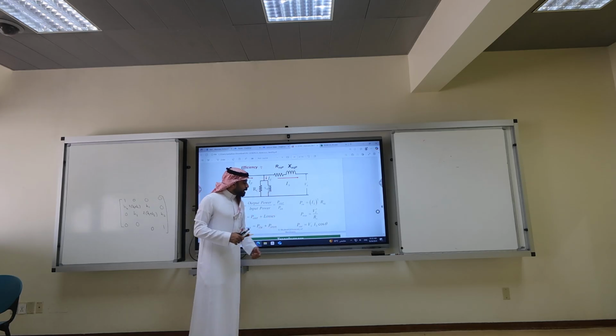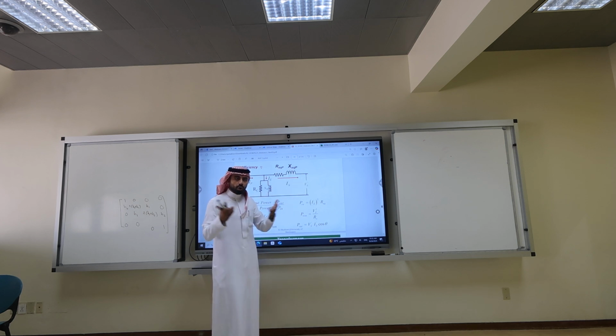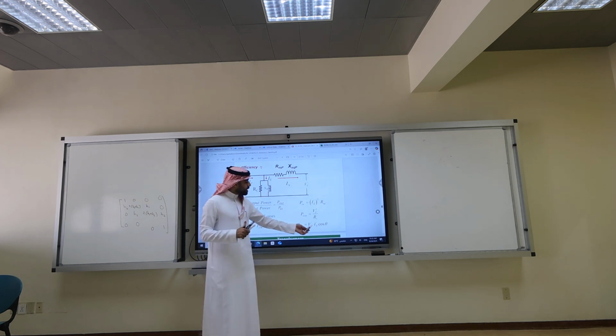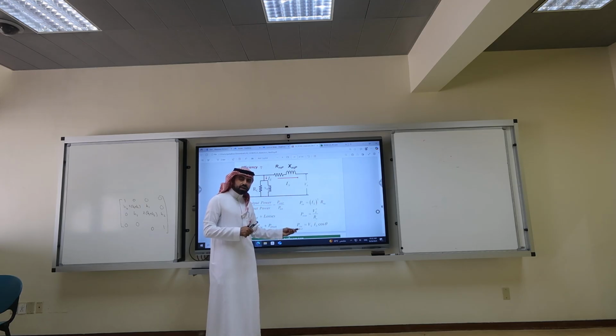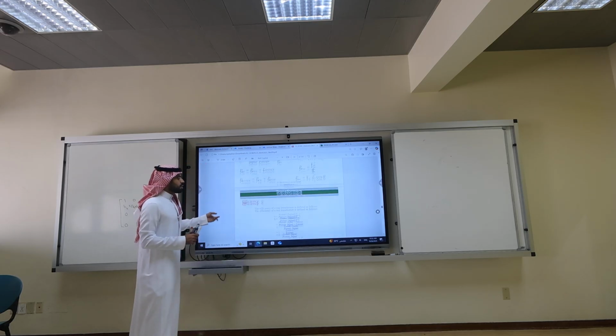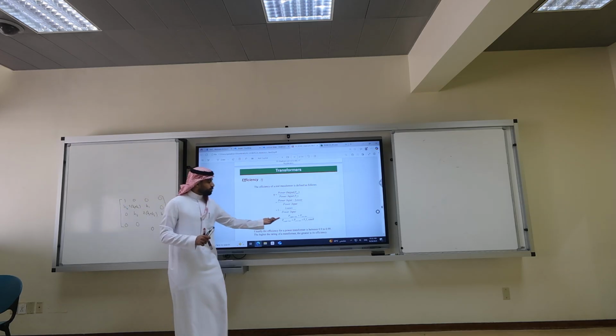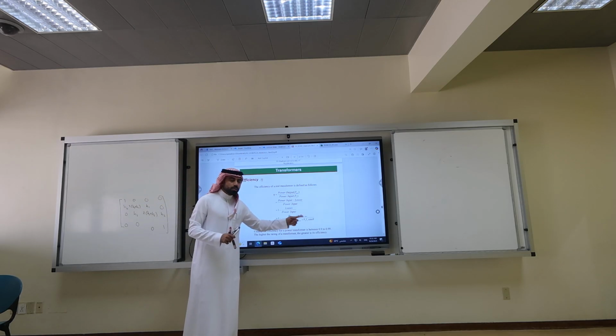What is the output power? It is V_S prime times I_S prime times cosine theta. Why? Because I'm referring the load now to the primary side. It's single phase, there is no three. So the real power output is that. If I combine these equations, I can have another general form that looks like that. But is this referred to secondary or referred to primary? Secondary. Referred to secondary.